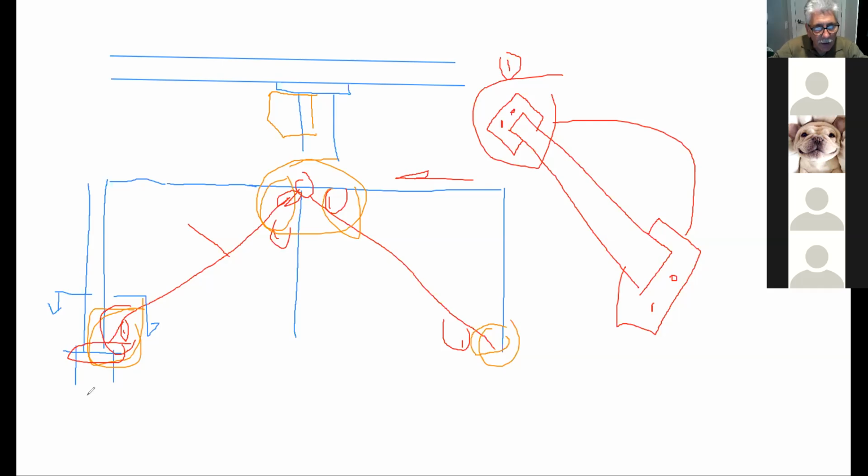Because basically, here if you want, you can make this cap plate the same thickness, but the geometry can be slightly different. Like you don't have to make it the same, but as far as your cap plate goes, what you're going to do is you're going to be bolting it there and bolting it there. See? So this is going to be bolted together, and therefore that's how the force gets transferred across these bolts, into these welds, into the brace, you understand? And that's how the whole load path gets transferred all the way down to your foundation.